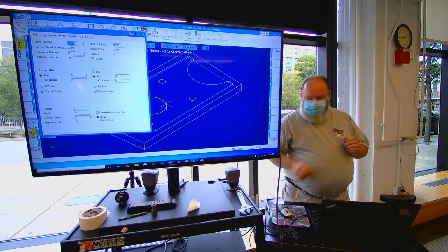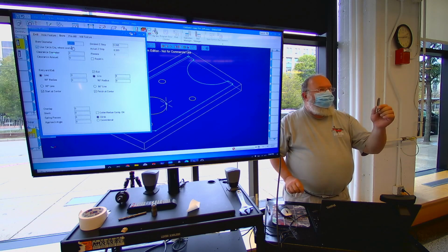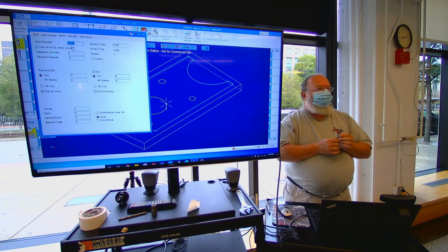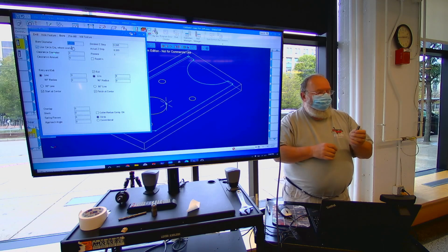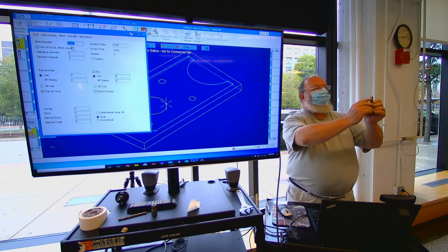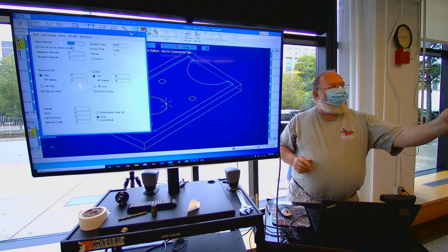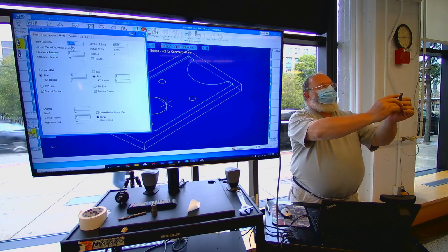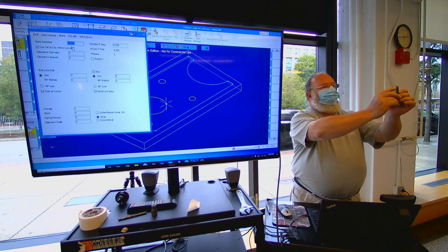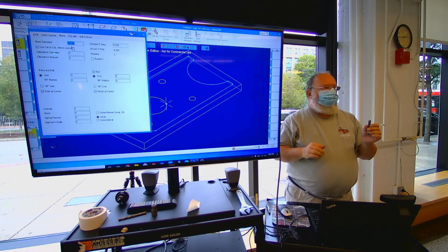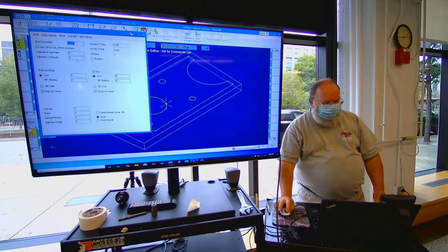Okay? Because a tap is a rotary tool that we drive down through a pre-drilled hole to give us internal threads. Okay? And I don't know if you can see it from there, but there's a shiny edge on the front of this tap, that's actually considered a chamfer. Okay? Well, you don't get full thread until you get down to here. And if you don't get full thread through the hole, then you can't put the screw all the way through the hole. Okay? And we'll get to that a little bit later.